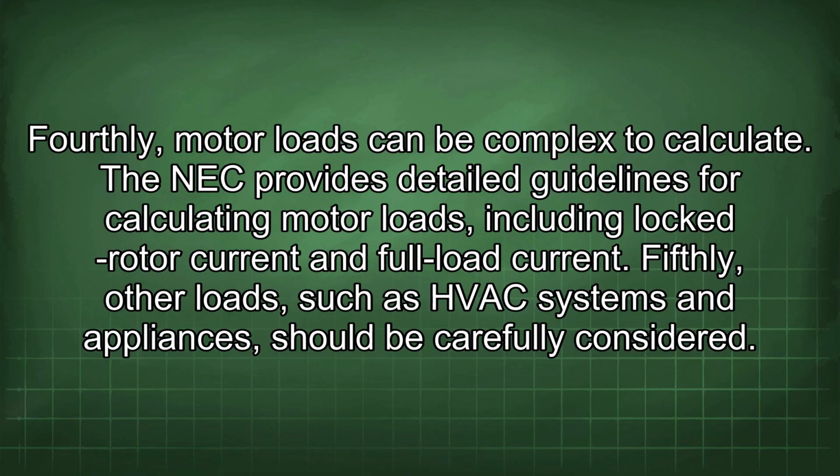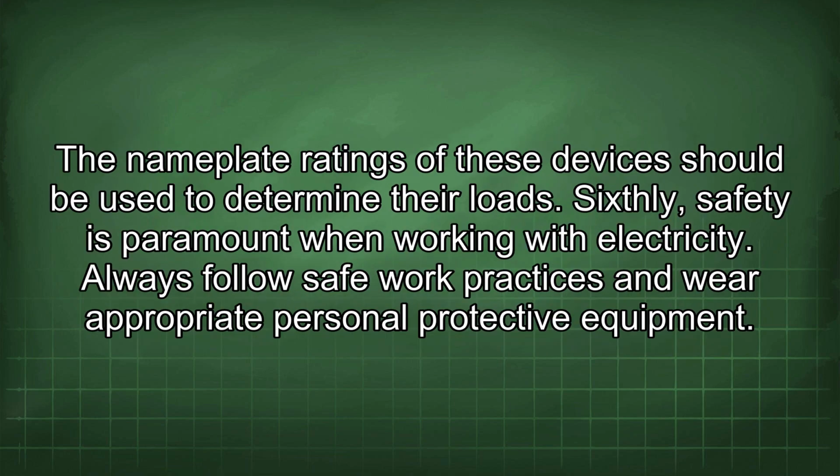Fifthly, other loads, such as HVAC systems and appliances, should be carefully considered. The nameplate ratings of these devices should be used to determine their loads. Sixthly, safety is paramount when working with electricity. Always follow safe work practices and wear appropriate personal protective equipment.